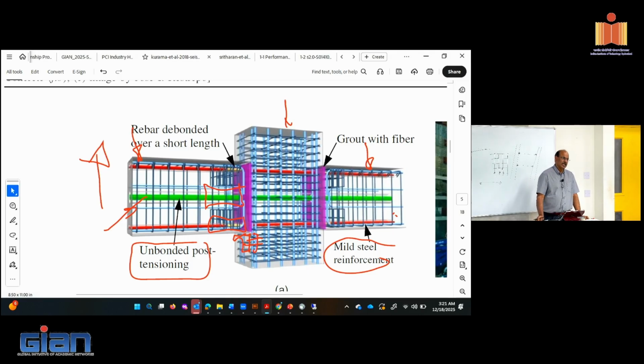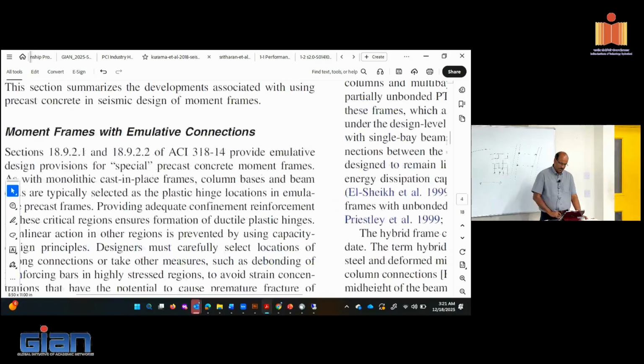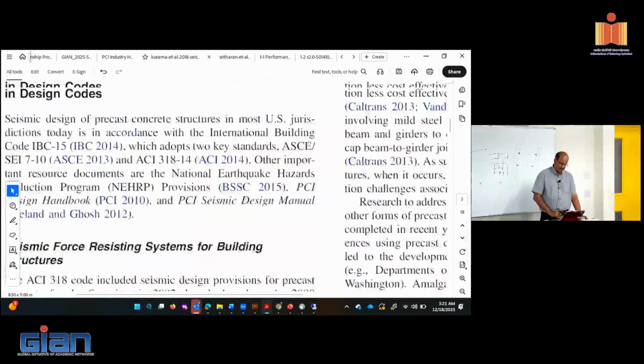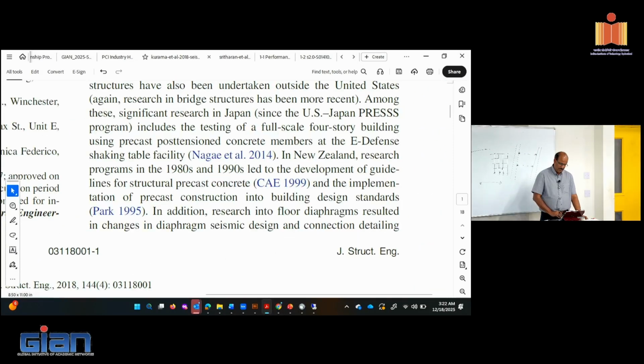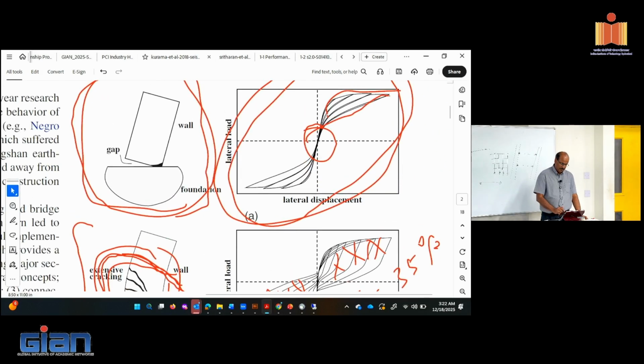The reinforcing steel itself will participate. You can design them to go through inelastic action. If you do that, they will add some additional energy dissipation to the system. So basically, what you're doing is you're going back to this system, what we looked at earlier, conceptually. Whatever we have here, it will remain similar, except that we will increase the hysteresis loop to bring in more energy dissipation.